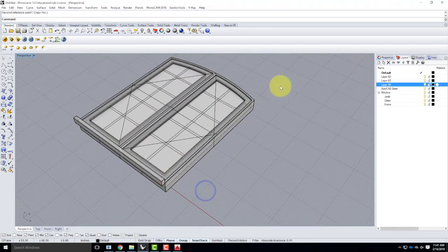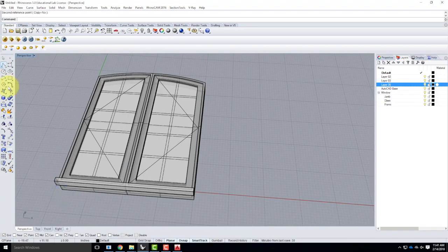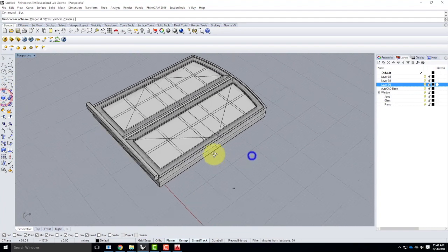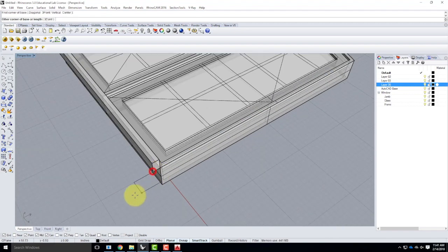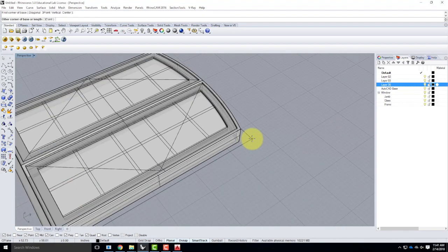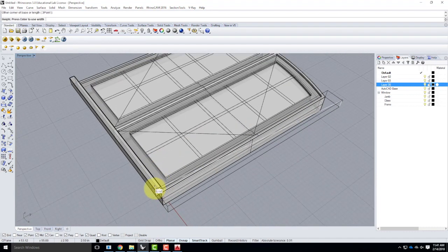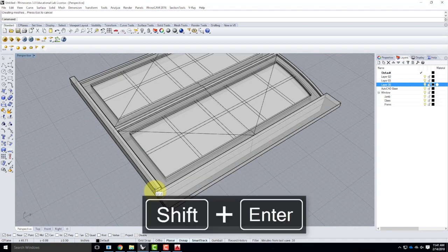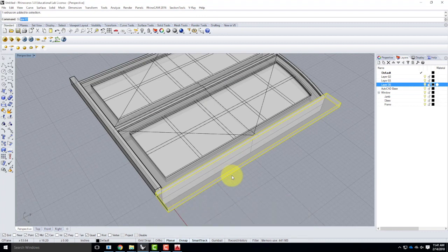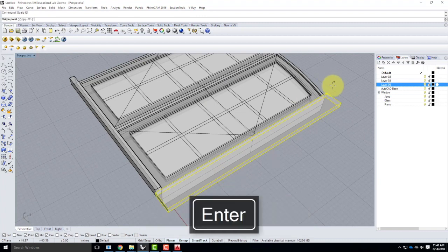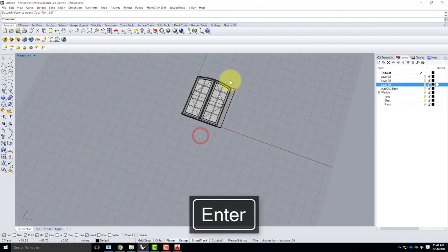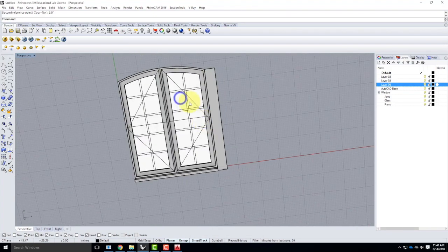And then we'll do some trim that goes around this on the upper sides. So I could do the same thing with the box. I could start right there, and I'm going to go here. I'm just going to be a little bit wide for right now, and I'll use that scale 1D. This would be 1.5 inches thick. But I want to control how wide that is, so I'd scale 1D and say I really want that only to be 5.5 inches, for example. So there's one side of the trim. Not too bad.